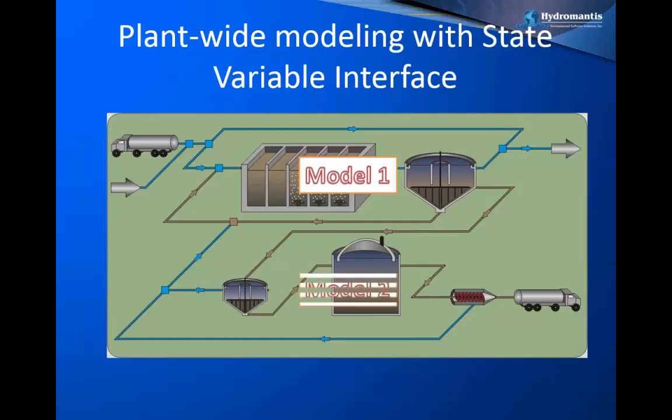Then when we come to anaerobic digestion, some of the species which are normally there in a liquid train system are not the ones doing the job in anaerobic digestion, and there are some specific bacteria which are working in the anaerobic digestion stage. Some of the states, basically with respect to substrate itself, are very different than the states which are used in liquid train models.